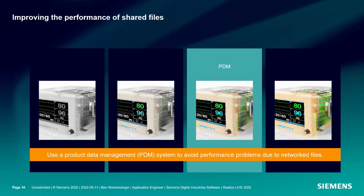Another common source of performance problems comes from referencing files stored across a distributed network. The best way to avoid performance problems due to networked files is to use a product data management system. PDM systems can be more cost-effective than many companies realize and can result in substantial performance gains.